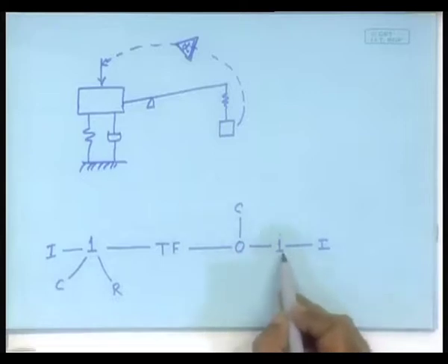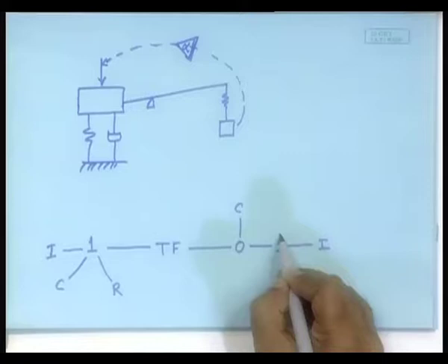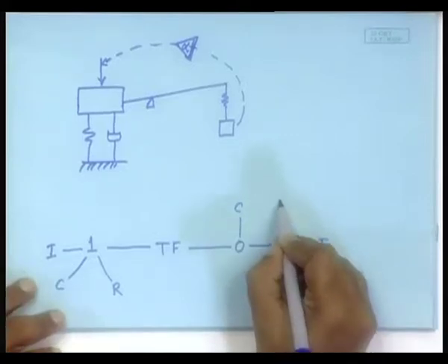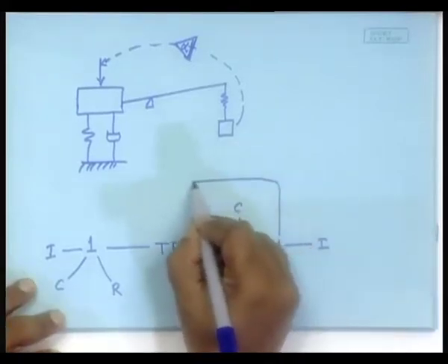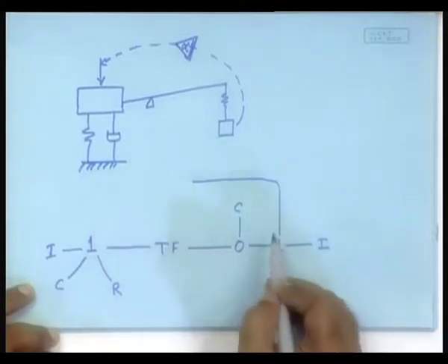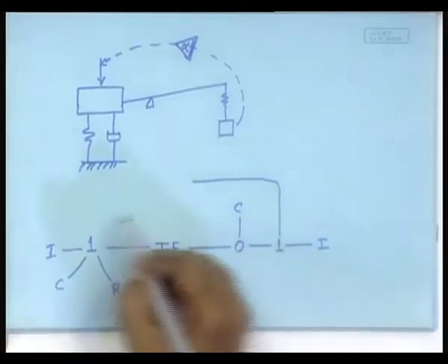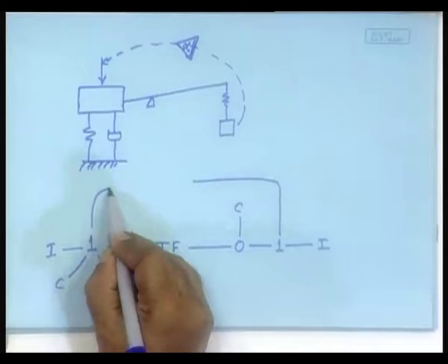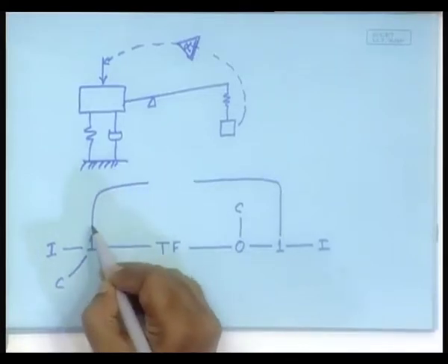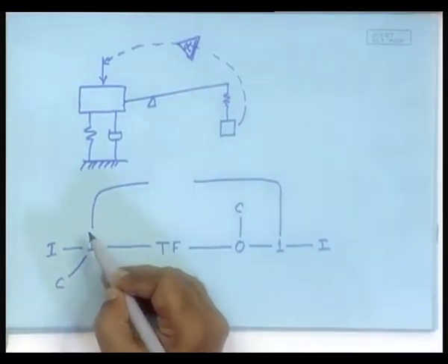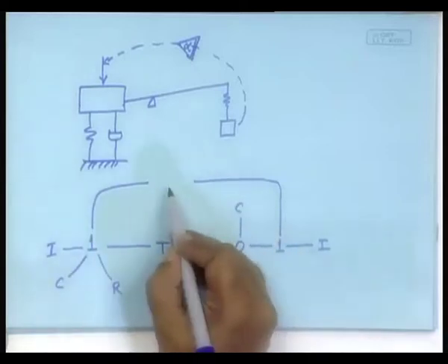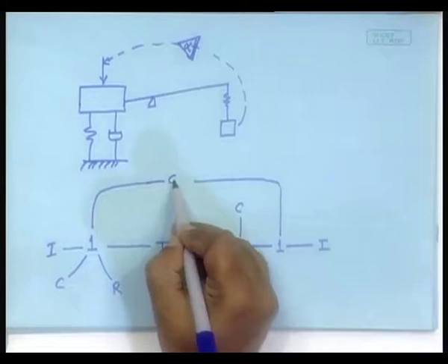At this point the flow is available. So, we are measuring the flow. So, what we will do is put a bond starting from here going all the way, but then here is a flow variable, and when it gets inputted here, what is it? An effort, it is force. So, in between you have to connect a gyrator. So, there has to be a gyrator in between.